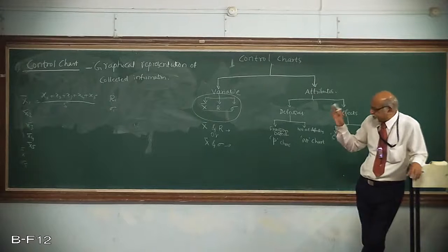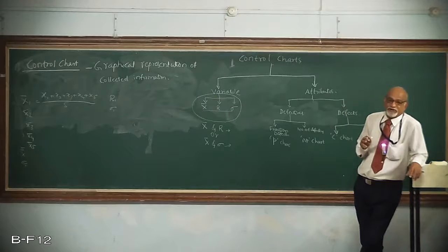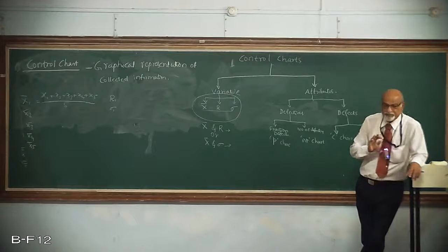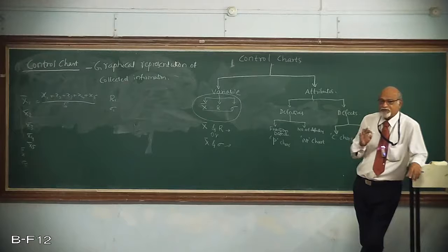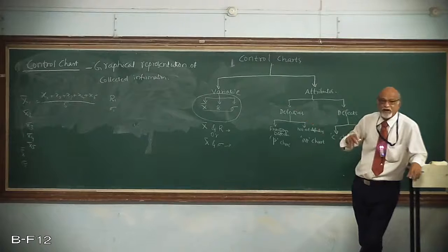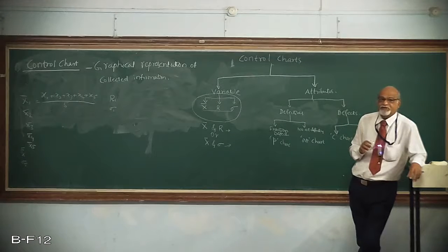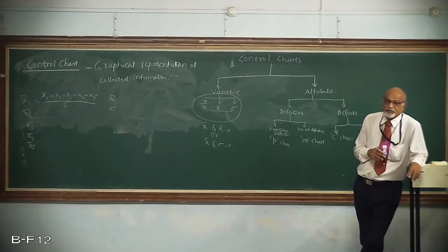But in any case, if the central limit theorem is to be applied, the individual values cannot be less than 4. Okay? But usually 5 is preferred. That makes it easier for me, so that I need not calculate the sigma value. I can use R. And at the same time, the calculation of the average value becomes very easy.